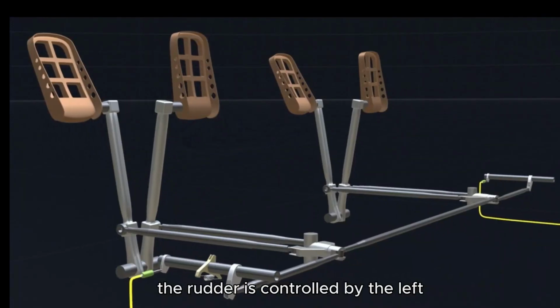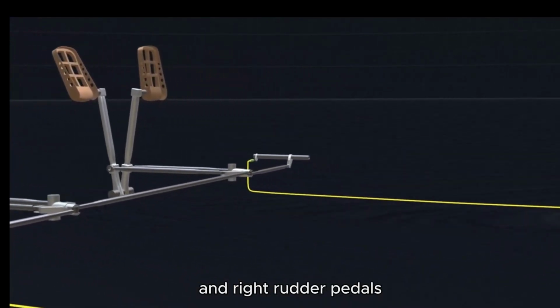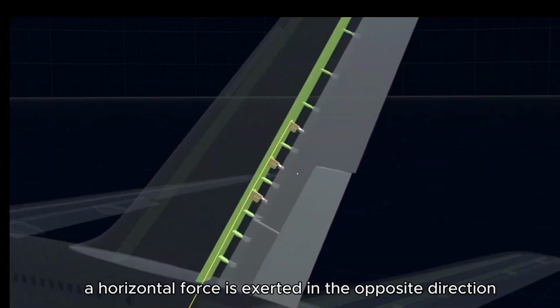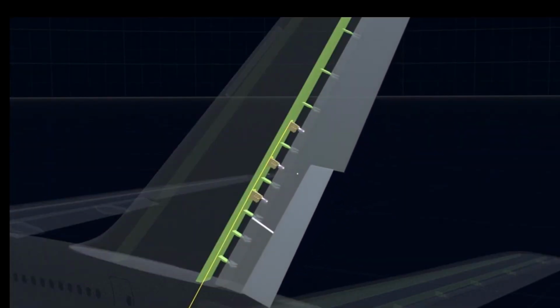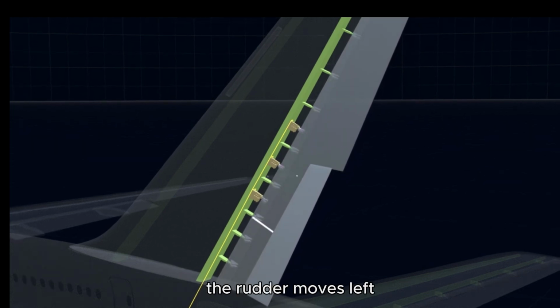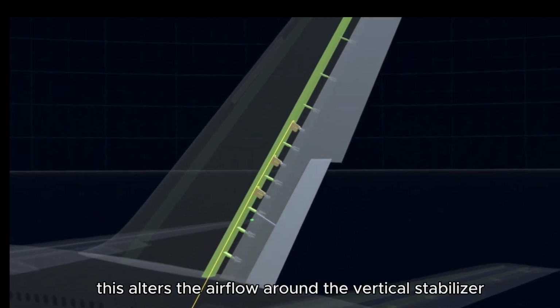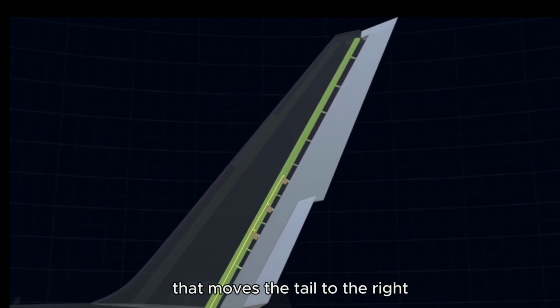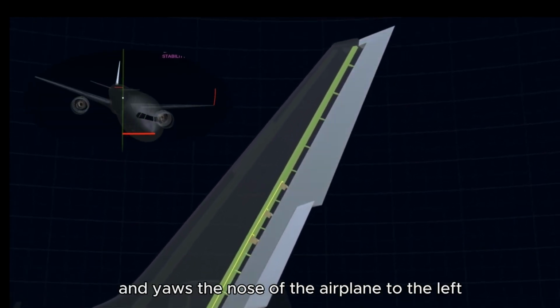The rudder is controlled by the left and right rudder pedals. When the rudder is deflected into the airflow, a horizontal force is exerted in the opposite direction. By pushing the left pedal, the rudder moves left. This alters the airflow around the vertical stabilizer and creates a sideward lift that moves the tail to the right and yaws the nose of the airplane to the left.